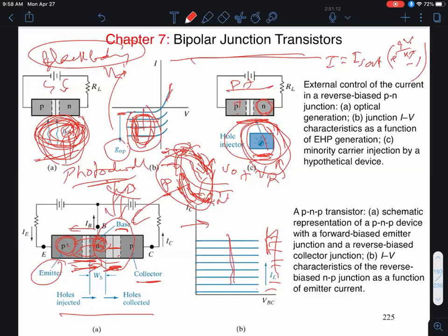Some of you might think, isn't that the same statement backwards? It's not, because I don't know if you remember, I had made a point of this when I discussed PN junction theory. If I ask you, okay, double for me the hole current in this emitter-base junction, what should I do to the structure in terms of doping? How would I double the hole current at this forward bias junction? Anyone remember that? Half the amount of N-type doping. Sorry? Half the amount of N-type doping.